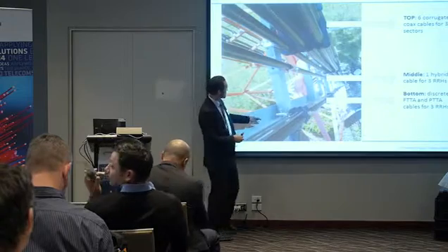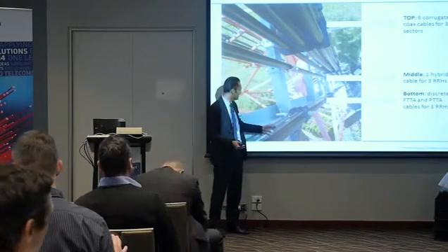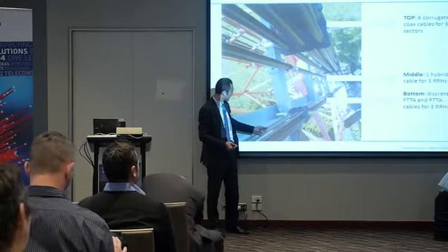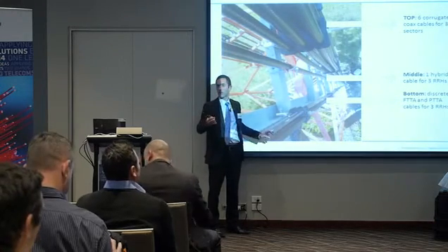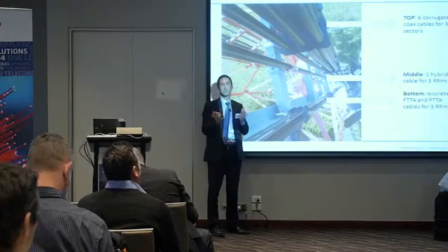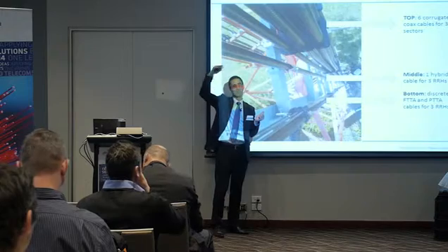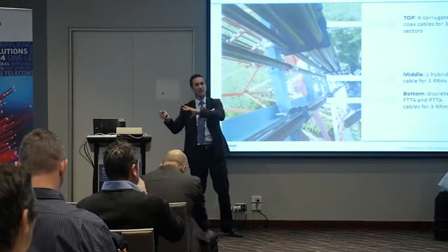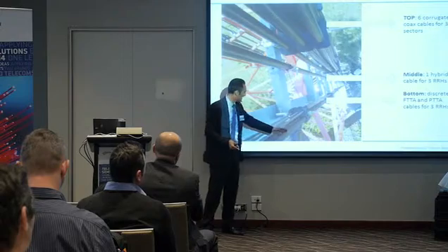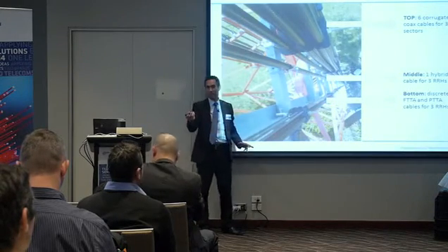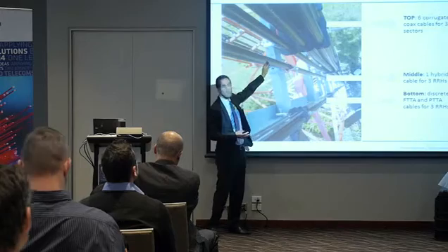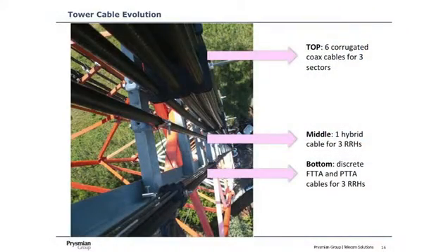And you have 2 ways to bring the fiber to the remote radio head. Either you are using a simple optical fiber cable, a typical riser, depending on whether it is an indoor riser for rooftop antennas, or an outdoor riser for towers. Or the power cables and everything are embedded in the same cable, like here, that we call the hybrid fiber to the antenna. Then it really depends on regions and operator strategies at this moment.